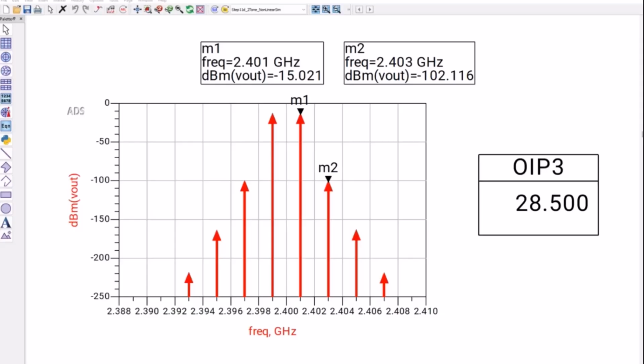Can a wide range LNA be designed from 10 kilohertz to 40 gigahertz? No, not with PCB for sure. If you want to do that kind of LNA, I would say look at MMIC. That's your only choice. Or look for some LNAs which you can get off the shelf from companies like Qorvo, MACOM, Skyworks, and so on. Could you provide all these files so that we can practice? Yes, the ADS workspace will be shared with you along with the slides which I have presented today.